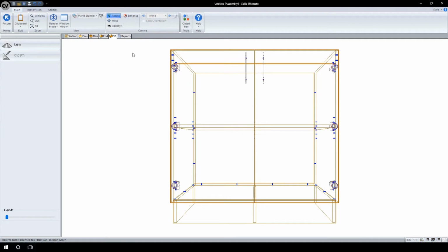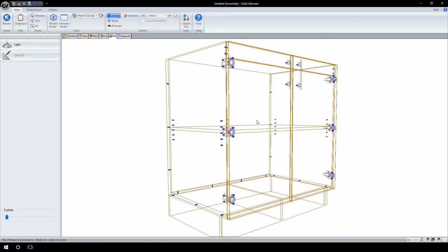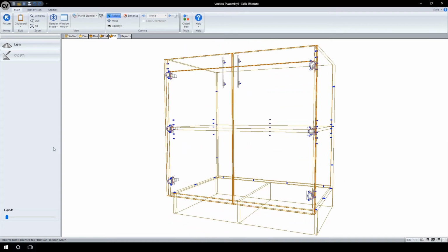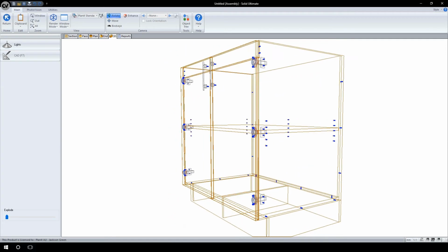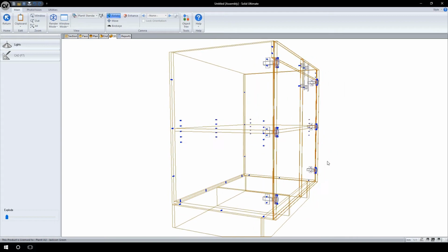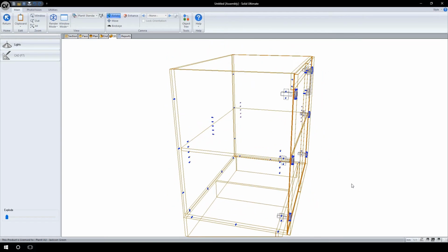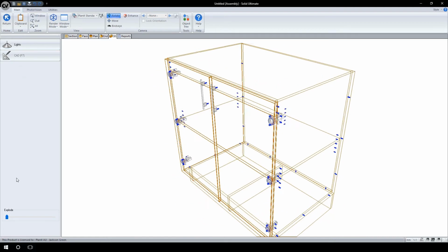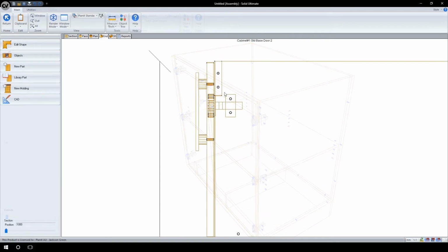What we can see is that despite only the Y position of the top stretcher having the proper equation applied, it conforms correctly to the sizing of the cabinet. This is because the part automatically had parameters applied to it when it was brought out from the cabinet library into the workspace. When we rotated the part, only the Y position was affected.